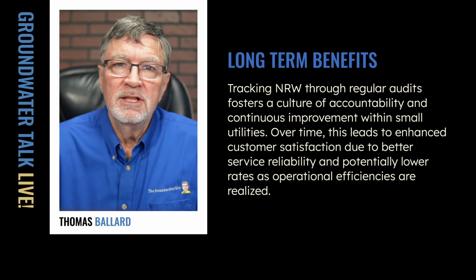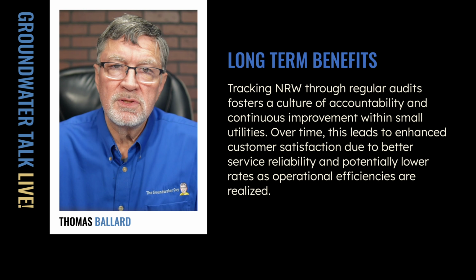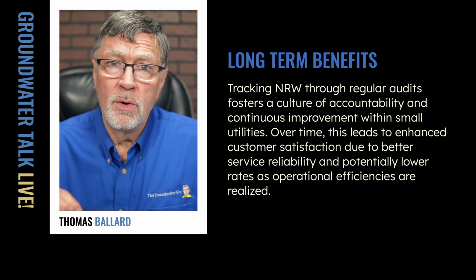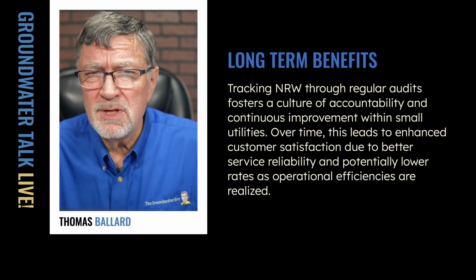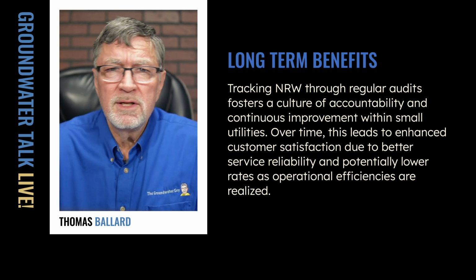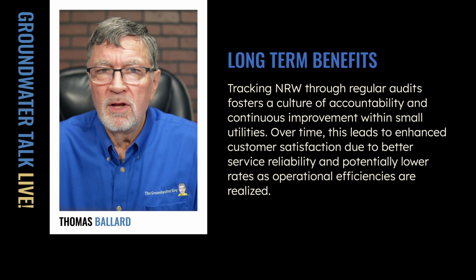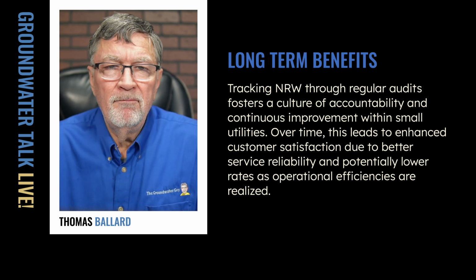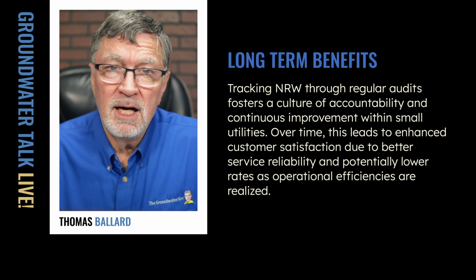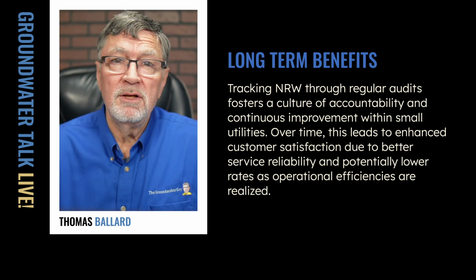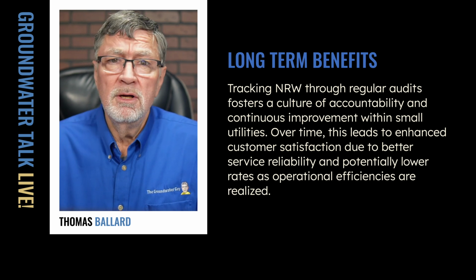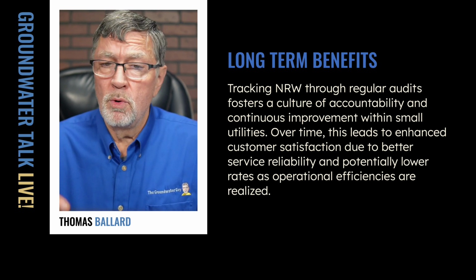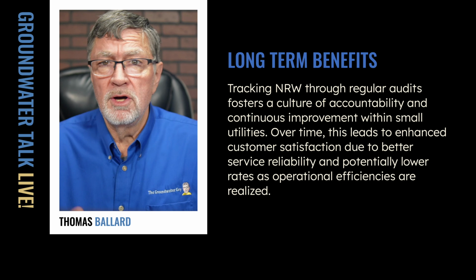So obviously, if your water losses percent is going up, and generally you want to try to keep that under 2% or less, 1 to 2% of water losses like that. But if that number is trending up, then obviously you need to go out and do some maintenance, track down those leaks, get them fixed, because that's money that's pouring into the ground and revenue that you don't have.